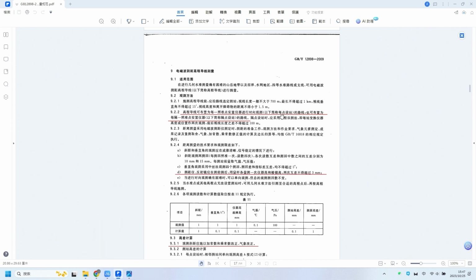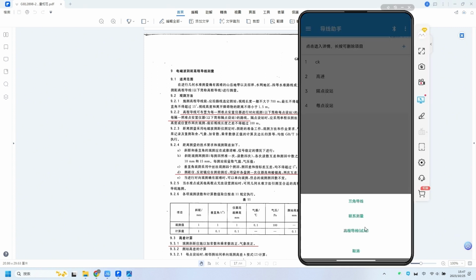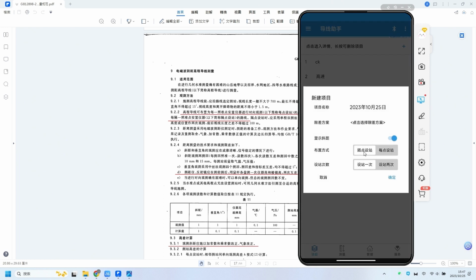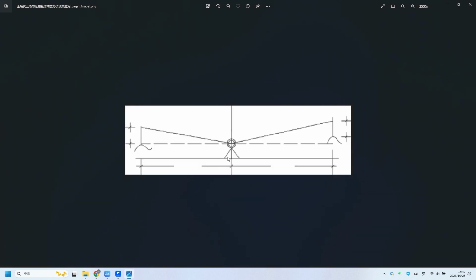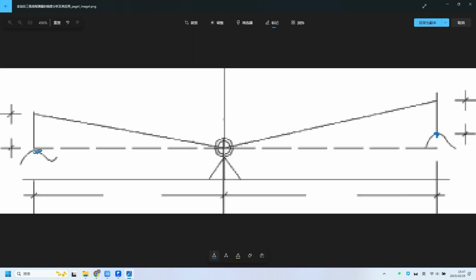Let's first talk about setting up a station at intervals, which is the second scenario. It is also the default method chosen by our software when creating an elevation line. Assuming we want to observe a height difference between 2 control points, and the target positions of the 2 control points are the same.